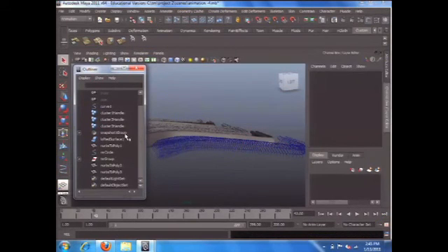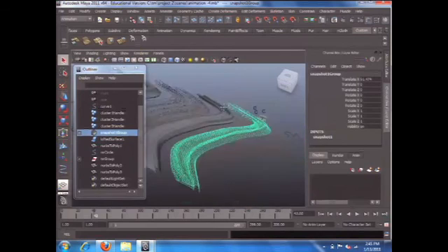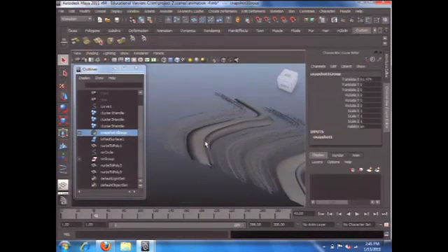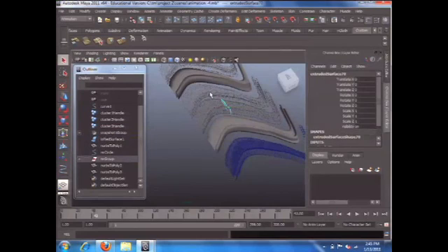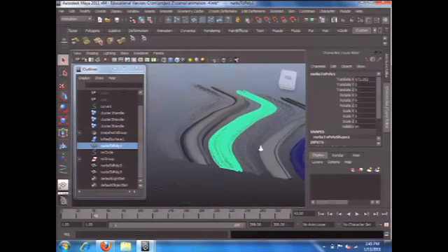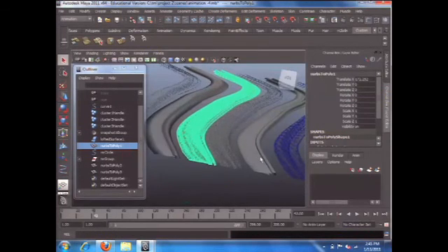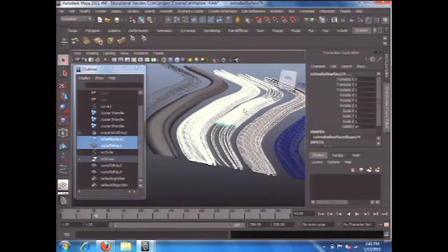Yes and no. I would say most likely you will get a computer crash if you just manipulate this. I would just go back and redo it with another snapshot. It doesn't take too long. The reason is there are some parametric features built in after you convert NURB to polygon. So if you change the density of the points, you most likely will get some error message when you convert that NURB to polygon again.